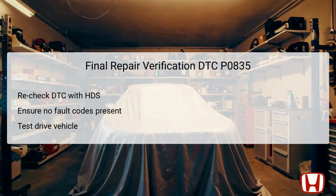This process begins with rechecking the DTC status through the Honda Diagnostic System, HDS. The technician should ensure that no fault codes are present after repairs to confirm that the issue has been successfully resolved. If any DTCs reappear, further investigation and repairs may be necessary.